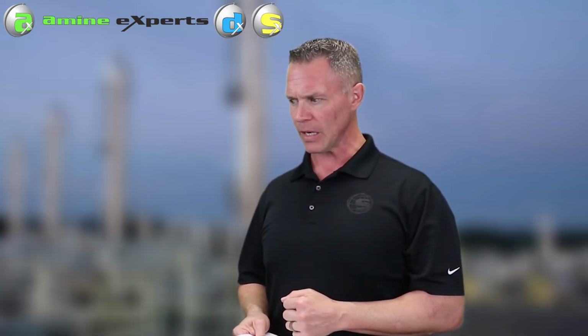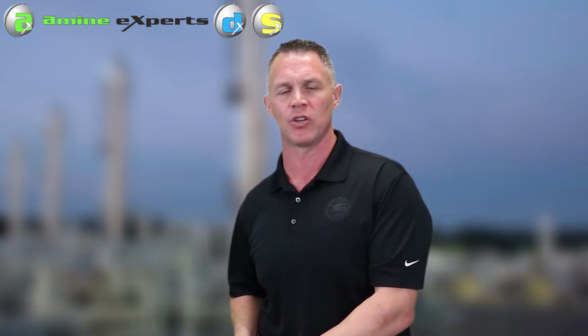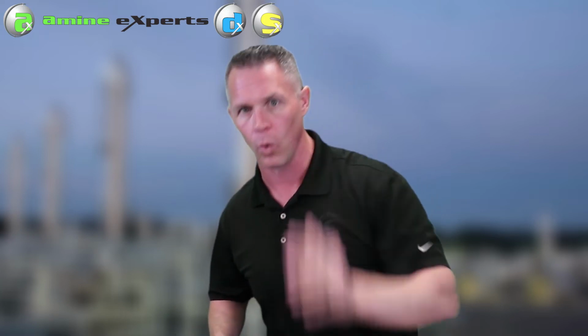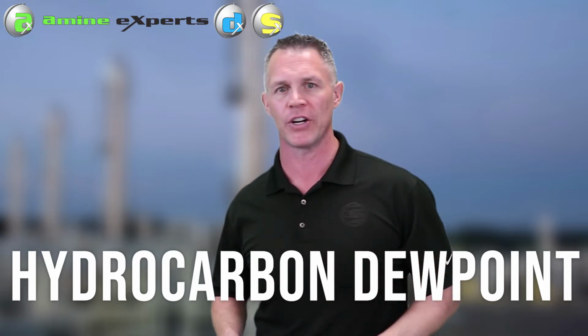But the question is, will you condense hydrocarbons, yes or no? And if so, at exactly what temperature does that happen? Rather than follow a rule of thumb, a much better operating strategy is to know the hydrocarbon dew point. You need to know the temperature and pressure at which your composition going through the absorber will either be a gas or a liquid or a combination of both.